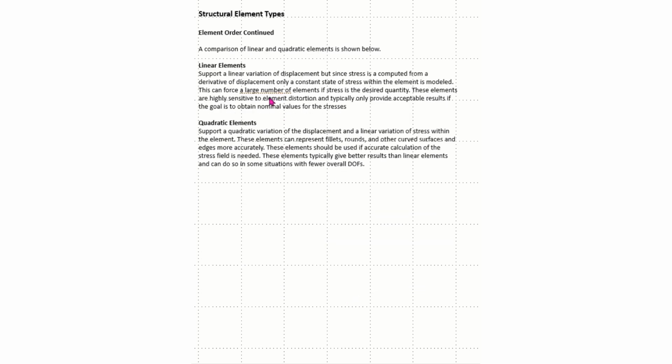So in linear elements, they support a variation of displacement, but since stress is computed from the derivative of displacement, only a constant state of stress within the element is modeled. And this can force a large number of elements if stress is the desired quantity. These elements are highly sensitive to element distortion and typically only provide acceptable results if the goal is to obtain nominal values for the stresses.